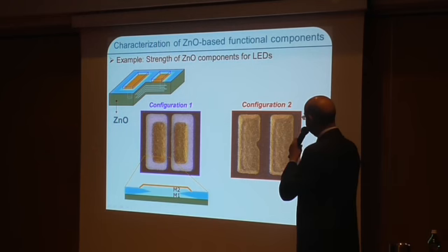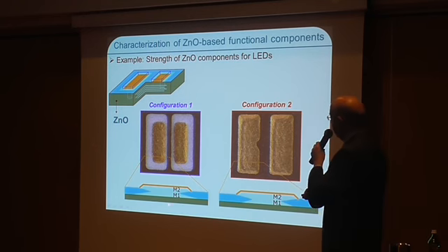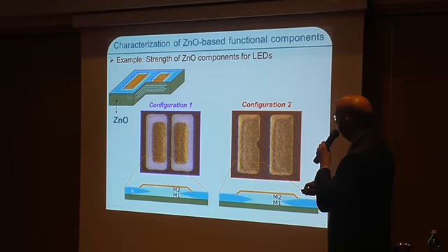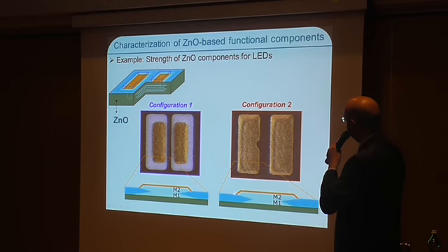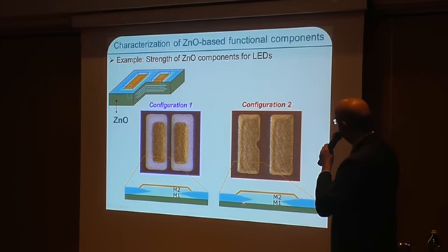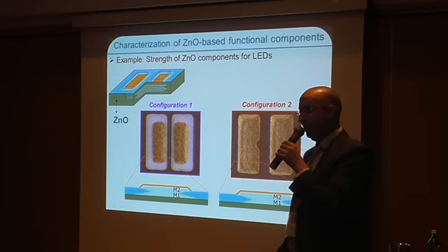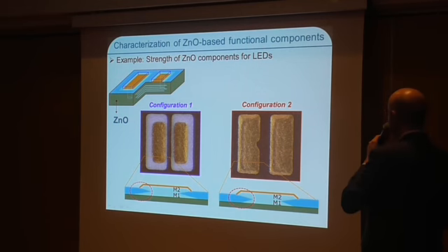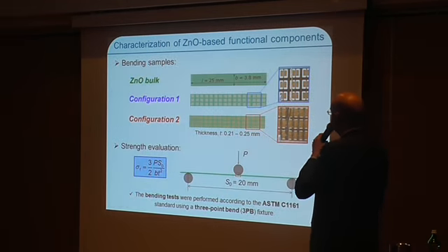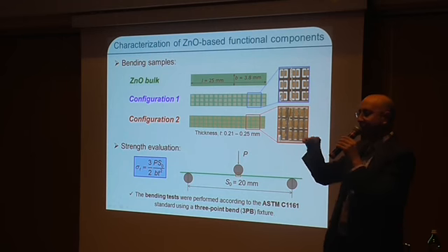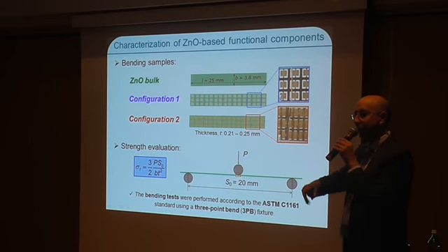In the other one, you have some metallization, the blue is the glass, and you can see the difference here, just a small tiny difference where the second metallization goes farther from the first one, and vice versa. We were doing some preliminary testing of these by axial bending, and we observed some dramatic differences between top and bottom.